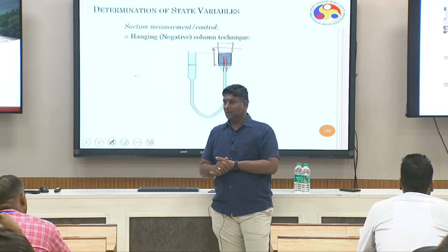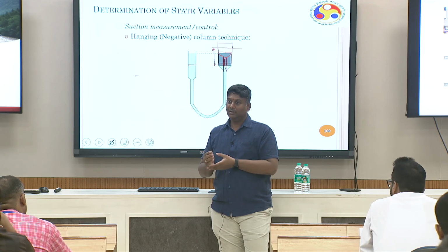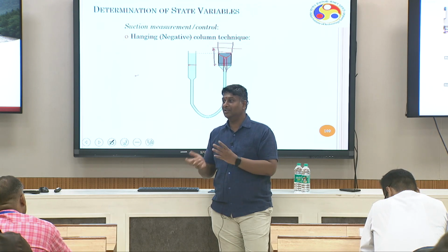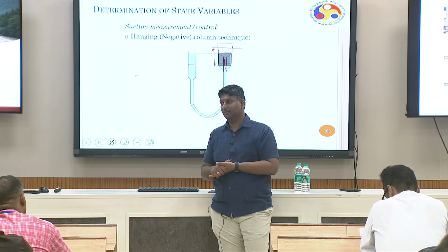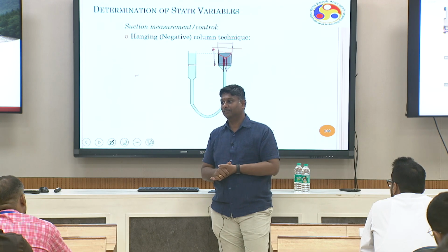So generally the contact angle varies within the soil mass. It can vary from 60 degrees to even more than 90, depending on the wetting or drying conditions. So that's the reason the hysteresis exists in SWCC.